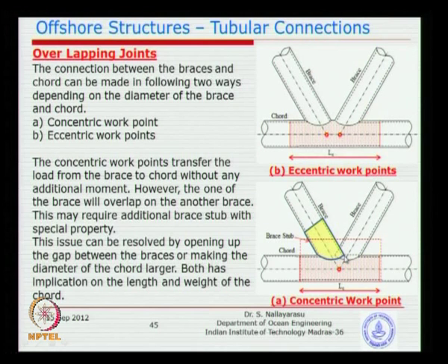If it is essential, then you look for a separate study, that means you will do a finite element analysis like what I have shown you earlier, try and do that kind of local analysis and then see whether you can resolve it, but most of the time no companies or owners will prefer this, because you see here this weld is unable to be seen after you finish it, because it is inside another brace. So, you cannot see the weld, you cannot inspect it, if a crack happens afterwards, it is going to fail, and that is why overlapped joints are not at all recommended.